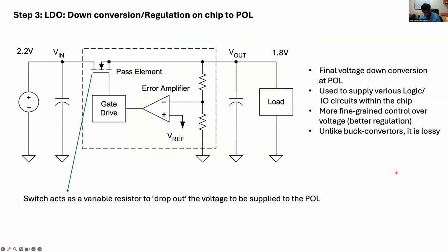Finally, just a little recap as we discussed. The 110 volt was converted to a 12 volt DC in the step down transformer rectifier stage, which was then sent to the DC-DC converter near the point of load, where it was converted to a lower voltage value. And now finally, the voltage that is sent to the chip goes into another voltage regulator component called an LDO that finally reduces this voltage from the input value to the target output value.